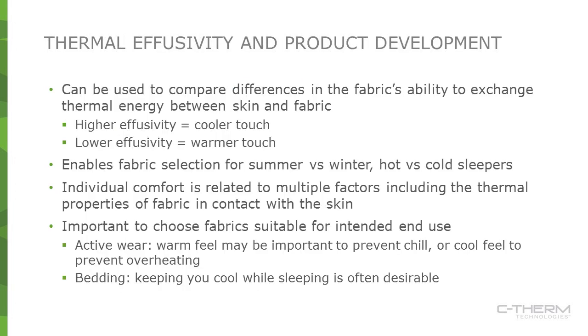So these slides are taken from an earlier presentation by Shannon's group, and they talk a little bit about the value of thermal effusivity in product development, that it can be used to compare differences in the fabric's ability to exchange thermal energy between skin and fabric. Again, higher effusivity having a cooler touch and lower effusivity having a warmer touch.